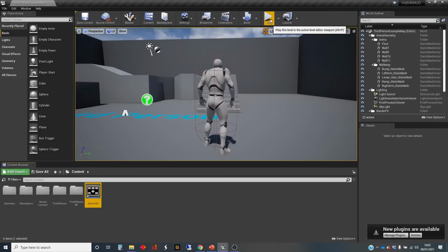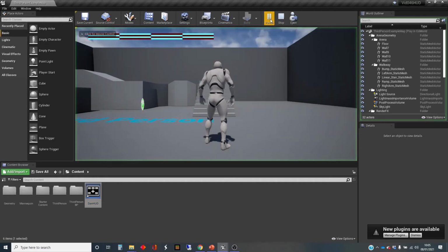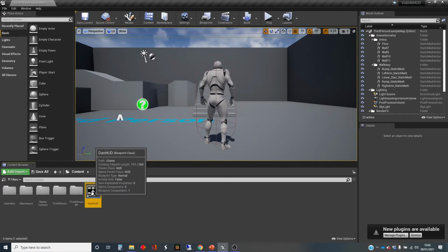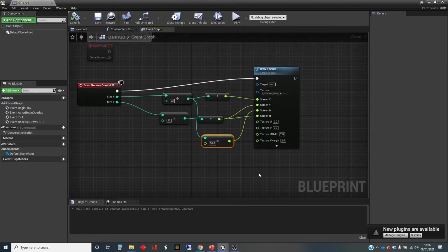What we're hoping is that the bar kind of looks correct. I'm not bothered about the texture mapping right now. Yeah, so that could be a reasonable bar across there. So I'm going to go back and look at the texture mapping now. So back in we go. And instead of doing it twice over the height, we want it once over the height. And we're going to make it 10 times over the width, because that matches the fact that I've stretched this to be 10 wide by 1 high.